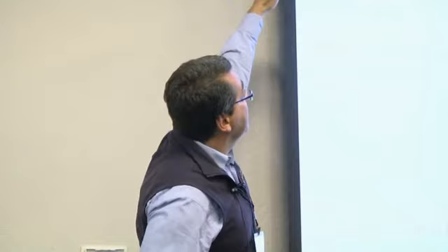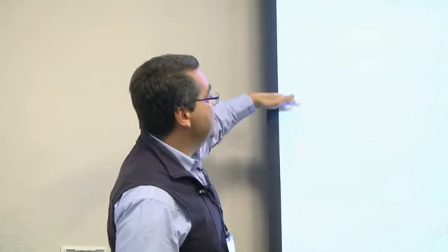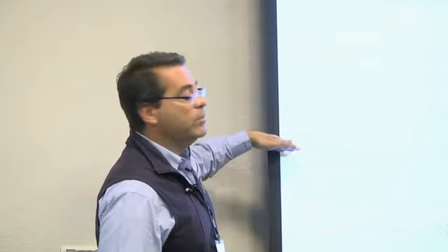Okay, not going to go through this, but these are the parameters that normally I use. The maximum applied water is DG max, the water holding capacity, a certain MAD, what we call the management allowable depletion, and the percentage wetted area and effective root depth and efficiency of application. So those are the parameters that are combined in a soil-based type of design.